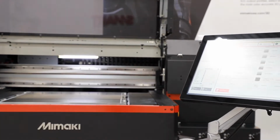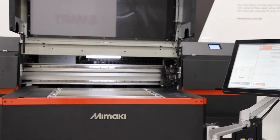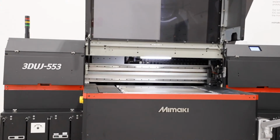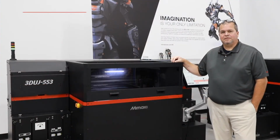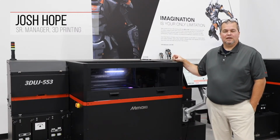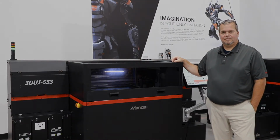This is the Mimaki 3DUJ553. This is our full color 3D printer. It's a large format printer capable of photorealistic output. This machine uses photopolymer resins. They're pre-pigmented. They start life as a liquid. They jet through a series of industrial inkjet heads, and then we UV cure them to a solid.